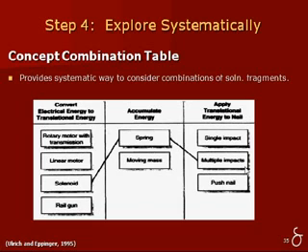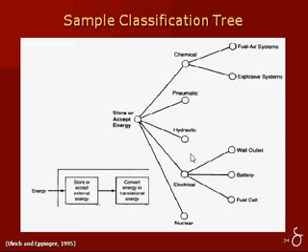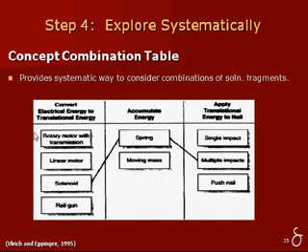So if I'm going to use a solenoid to convert electrical energy, so we've actually pruned down here, and we're going to say now we're going to use electrical energy. And there are different ways to apply electrical energy and convert it to translational energy. We can use a rotary motor, a linear motor, a solenoid, a railgun. And each pathway through accumulating energy and applying translational energy to the nail, each one of these is a possible concept.